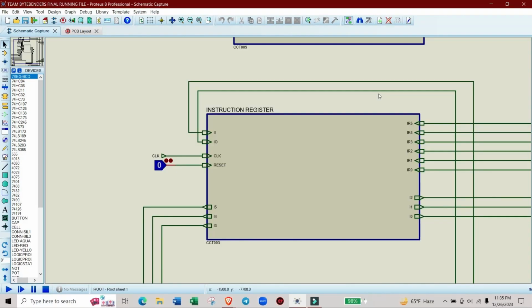Instruction register. It holds the current instruction so that it can decode and give input to the control and timing unit. Specifically, the instruction register holds the opcode which defines the type of instruction. The function of the instruction register is to receive and store the 6-bit instruction placed on the bus from the RAM. The contents of the instruction register are then split into 3-bit segments. The upper 3 bits go into the controller sequencer, while the lower 3 bits are sent to the bus.